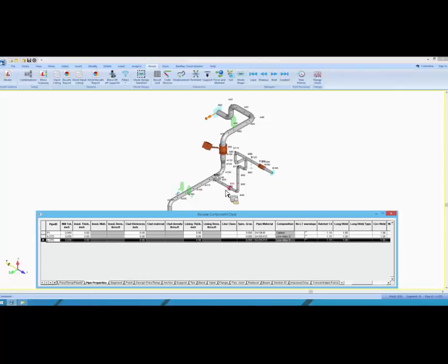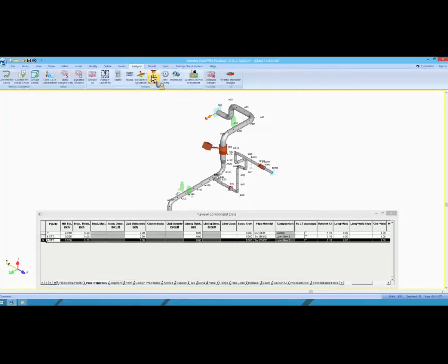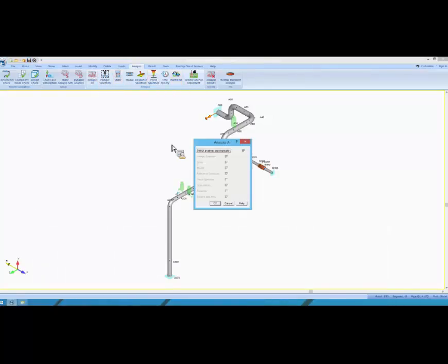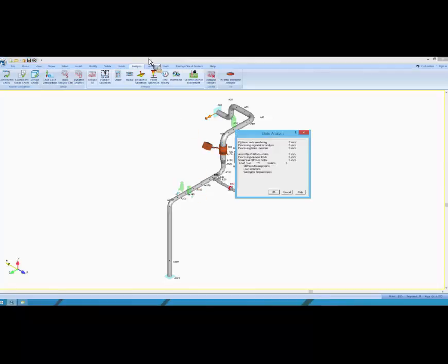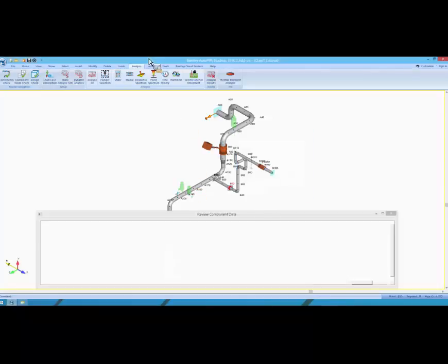We have only a single flange in this model at B30. So we would first perform an analysis of the model so that results are available, which would then be used by the flange analysis to perform the flange design.